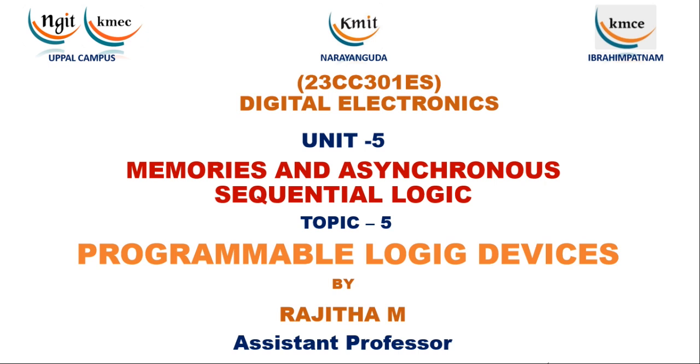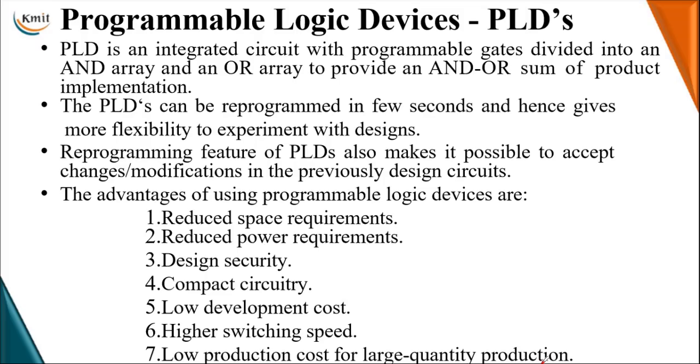Hence these are called combinational programmable logic devices, and these are available as integrated circuits which can implement the Boolean functions, in standard SOP or in simplified expression, using an array of AND gates as well as OR gates.